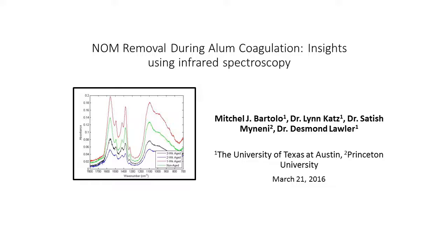But now if you can drop the coagulant dose and use less DBP precursors and save some money in coagulant, because now, wow, with aeration, I've gone from 60 parts of total THMs to 40. Wow, if I remove my coagulant dose, I can go back up to 60. They're smart enough to do that. Well, it depends, if they're really trying to justify. Because their coagulant dose is mostly driving turbidity removal.